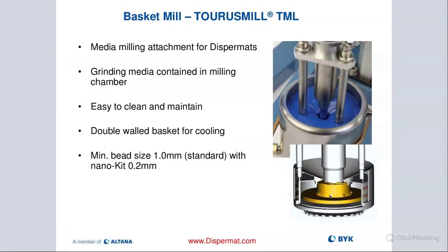And then on the bottom, below the milling disc, is actually where we have our screen. And right outside the screen, we have a Cowles blade to help us draw the mill base out of the basket through the screen, basically keeping the beads back inside, and then push or pump the material back to the top of the mill. As you can see in this picture, right above the milling disc is another disc.